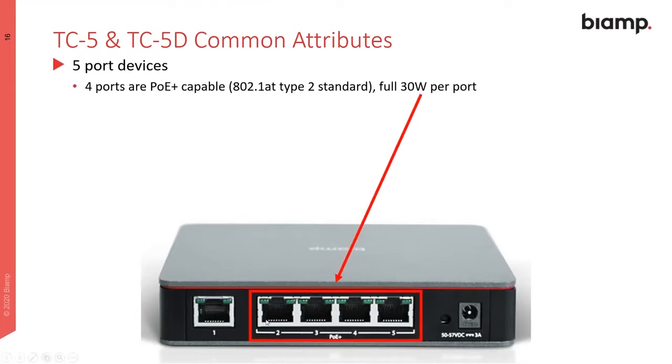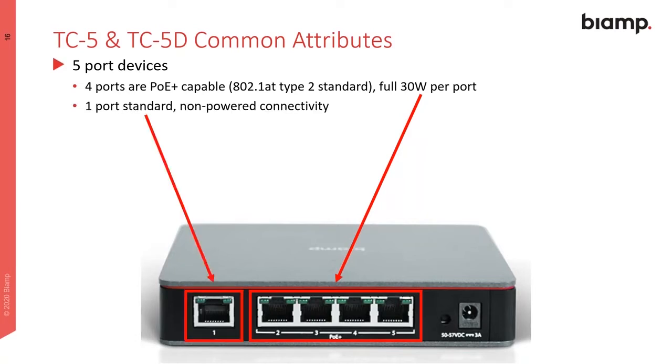Remember that ports 2 through 5 are 802.3at Type 2 standard, which is capable of a full 30 watts per port. So you can drive a 30 watt PoE Plus device. Port number 1 is a standard port, with non-powered connectivity. So this can be connected to your server class device.